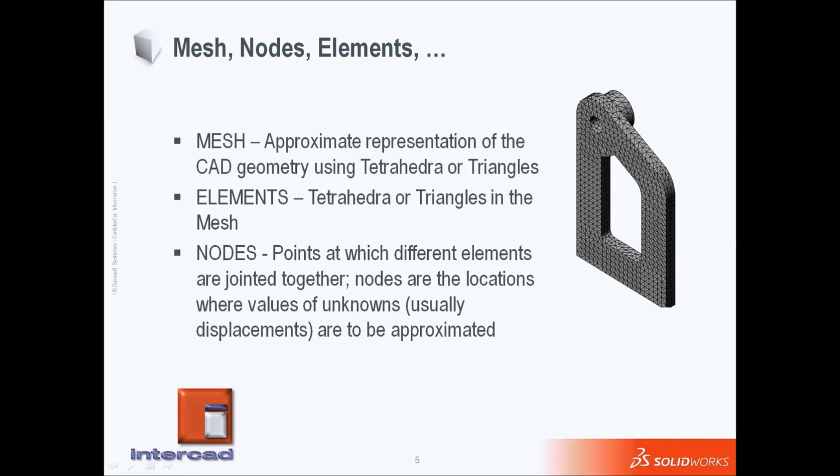So what we do in finite element is put a measuring tool like an element, where the shape is tetrahedral or triangular. Then all this together will represent our geometry. The connection points are nodes, and then we apply our boundary conditions, the physical conditions of the part, like force and everything else.